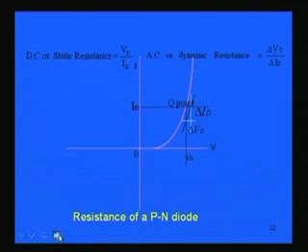Now, from this diode characteristic we can also find out the resistance of the diode. When you have the VD-ID characteristic and want to find the resistance of the diode, mind that it is a non-linear characteristic. The diode is not linear; only in the higher portion of the current region can we assume it to be almost linear, but practically it is not linear.